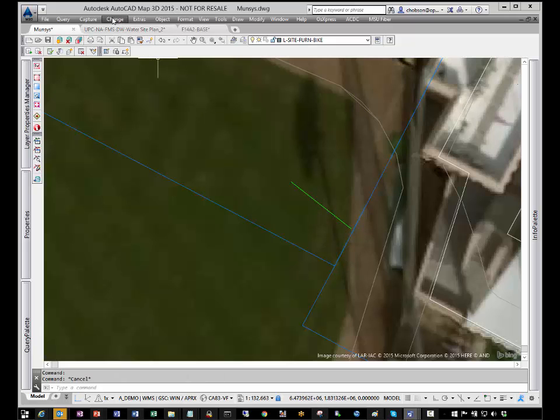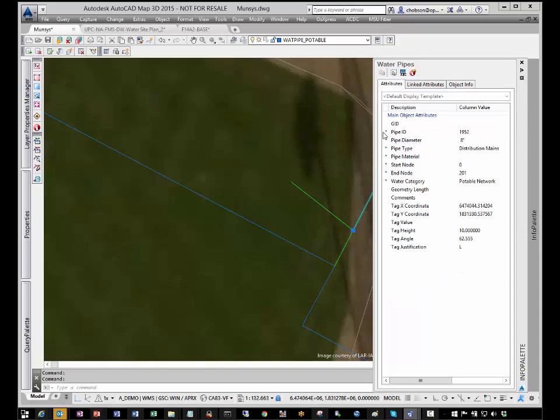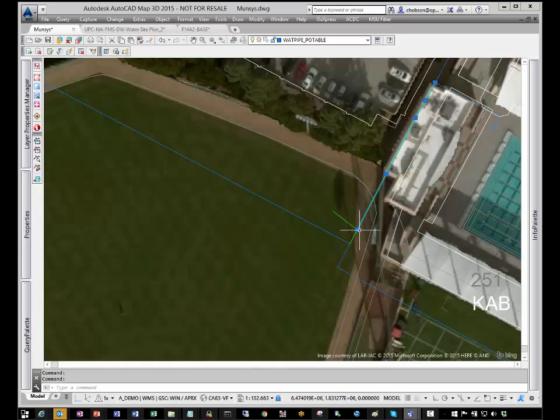I could come in and say, you know what, I need to extend and break pipe. So it says select the water pipe to break, very easily. So we select this guy, and there's the pipe to extend. And now it's created 2 new segments and automatically done that. So it just works like CAD. That's the same way you do an extend and break in CAD. Show the subject and then do the change. And you'll notice that it's carried over these things in asterisk, so all the characteristics of the original pipe. So it just does a powerful job of building out those data sets.